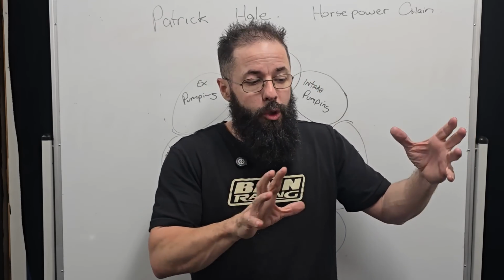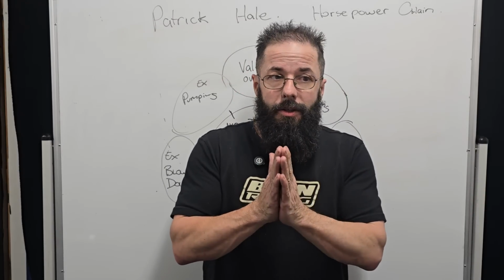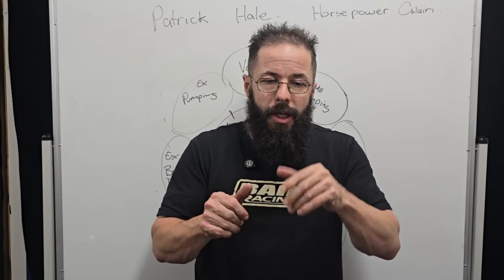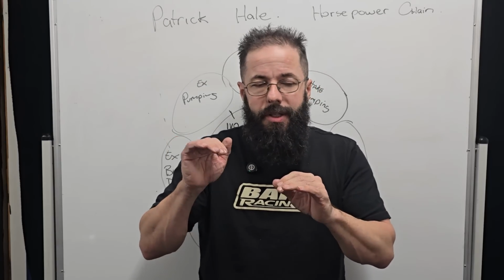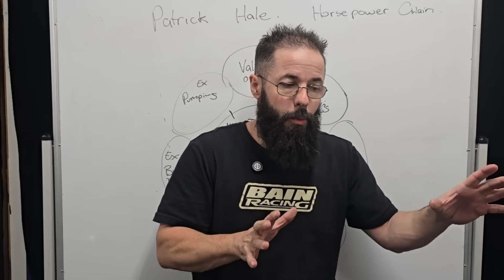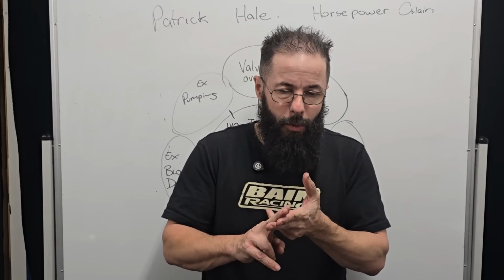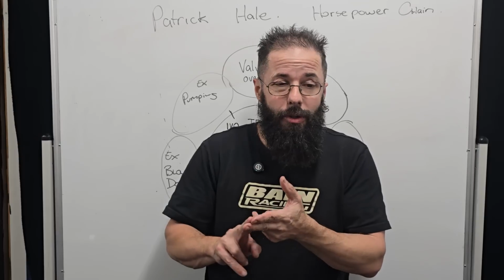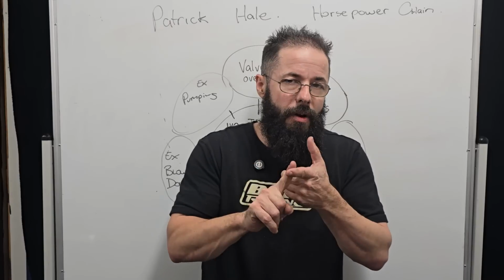So you would see some really, really lazy masters, and even before you get into what Dave's doing with the Spintron, because the Spintron will tell you far more than what your cam spec guys will tell you on where it is, depending what their initial is, whether it's 6 thou or some guys 10 thou, whatever it may be, and you're at 50.